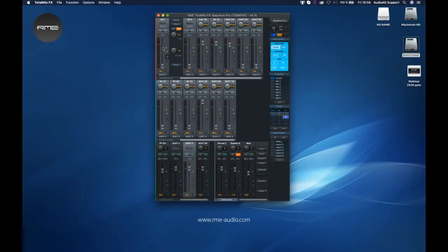But you just take down the phantom power and the gain, and you can use this now as a line input. Easy as that. Even if you have a very hot signal, you can even do a 20 dB pad, and you can even lower the signal. So you can just connect it directly to the input and use the preamp of your choice. That's no problem at all.